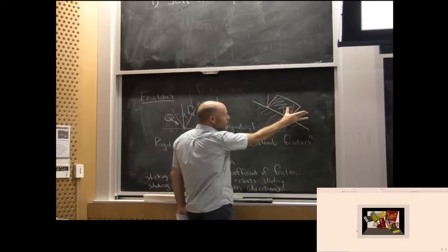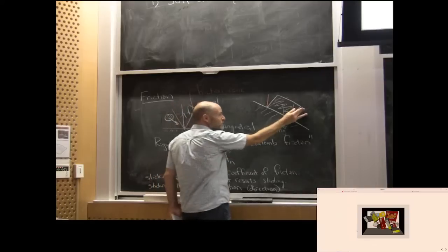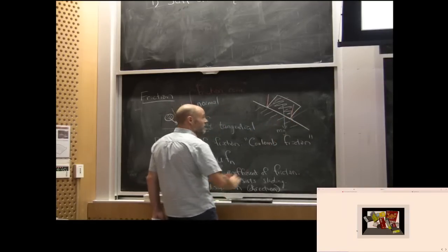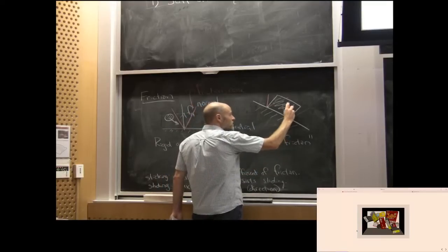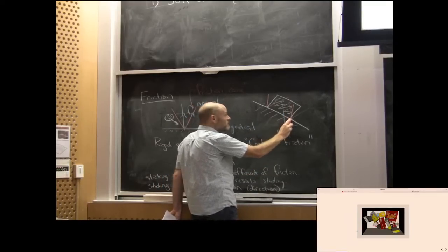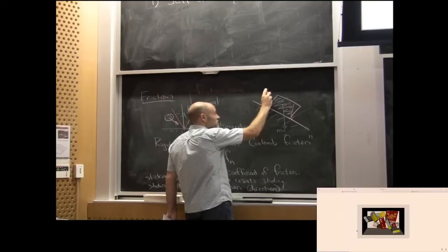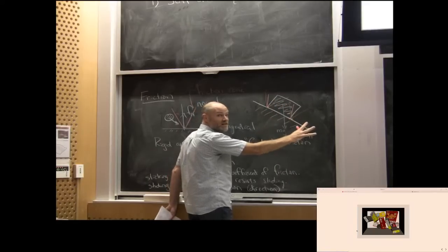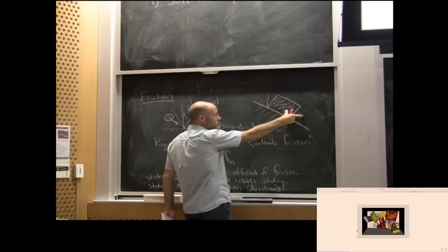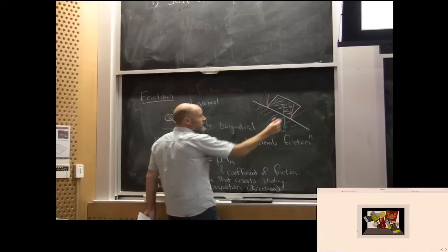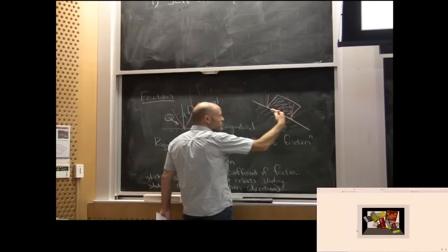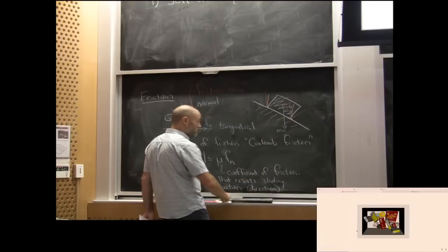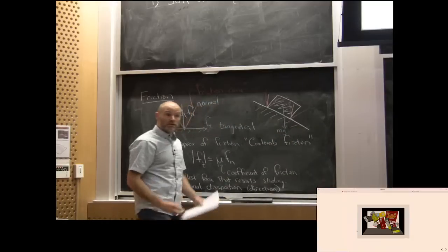If my mu was larger, my friction cone could increase. Do you see the geometric picture I'm trying to say? In order to get force balance, I would need a force of friction that's perfectly resisting gravity. Since this is outside my friction cone in that picture, that means that thing's going to slide. If I were to increase the friction cone by increasing mu, then I could get inside that. Or if I were to decrease the ramp, I could get inside that. But there's actually a beautiful geometric version of friction in that picture.